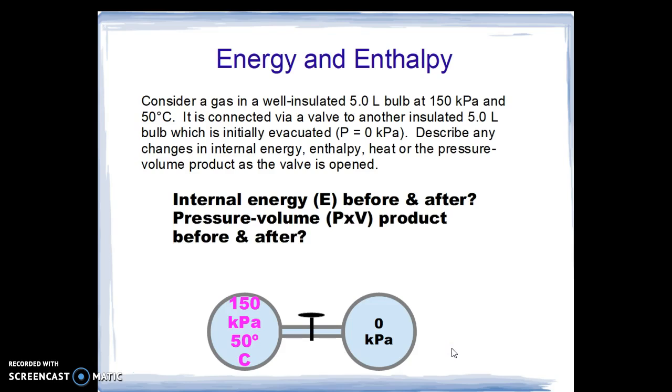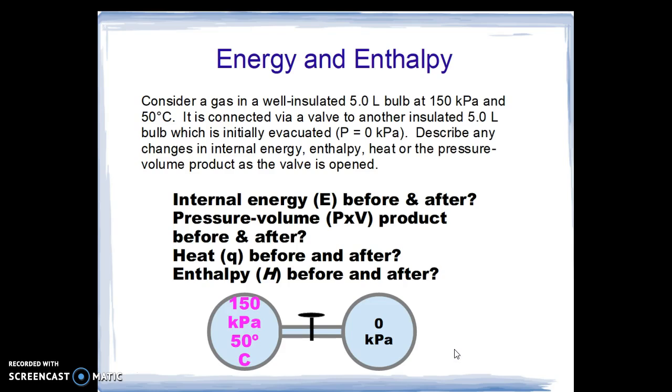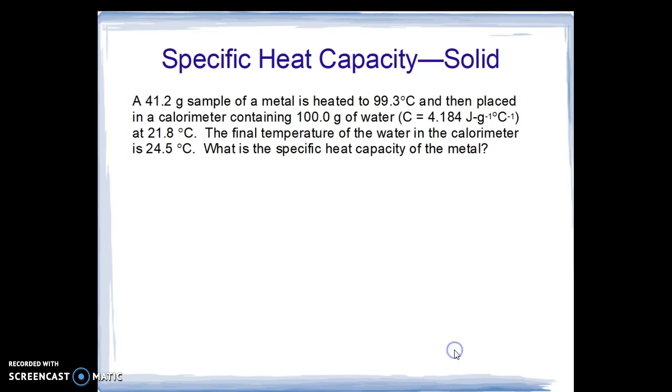Pressure-volume product stays the same. Heat: it's well insulated, so we have not been able to transfer any heat in or out. Therefore, because of the definition of enthalpy, there is no change in enthalpy in this system when you open the valve. This is counterintuitive, but it is true.